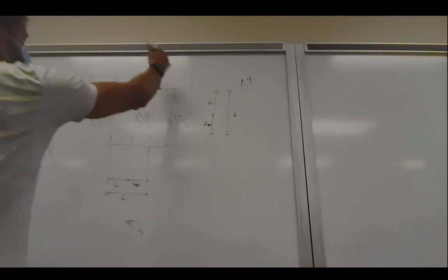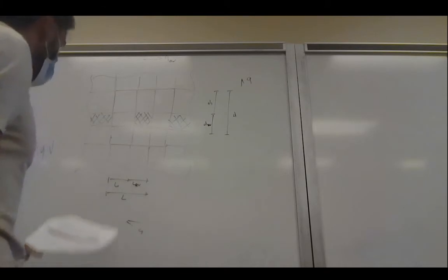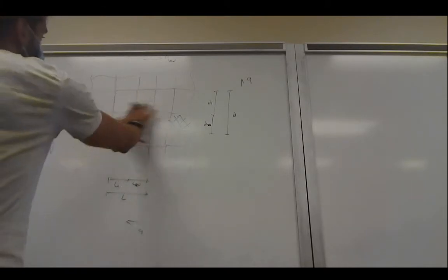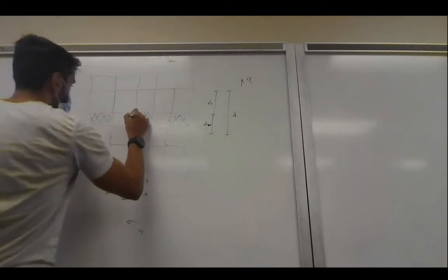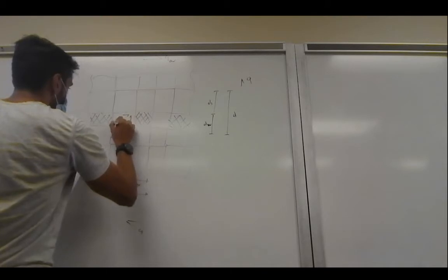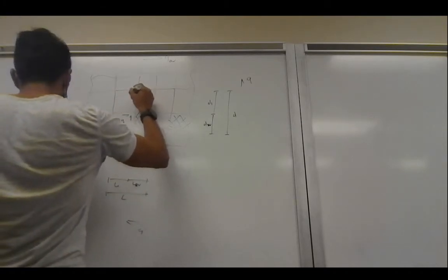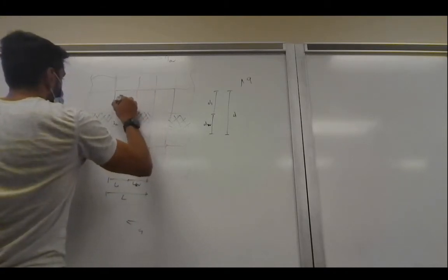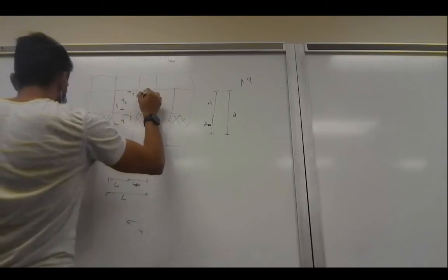So we have some average shear flows given at the ends, and we have some geometry given here. And then the idea is to determine the shear flows in the surrounding panels around our cutouts. We're going to focus on this 3x3 grid for now only. So let's define that. I think this is Q1, and then what we have here is Q3, and this one is Q2.